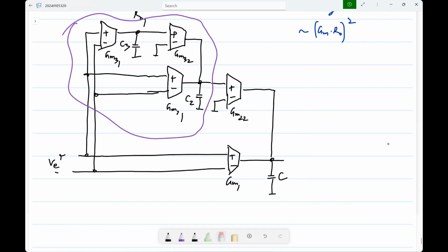And of course, you know this type of op-amp, that type of op-amp, there is no need to be shy about marrying them together. So you can use that op-amp in this or this one in that. Of course, finally, the point is when you put in all the engineering details, it has to be useful. To generate topologies at the control source level, quite easy. But of course, there has to be some use that you do the analysis, simulations, and find out. But the thing is, you can potentially use a Miller op-amp there or vice versa. Okay, the inner part of that Miller op-amp could be this.